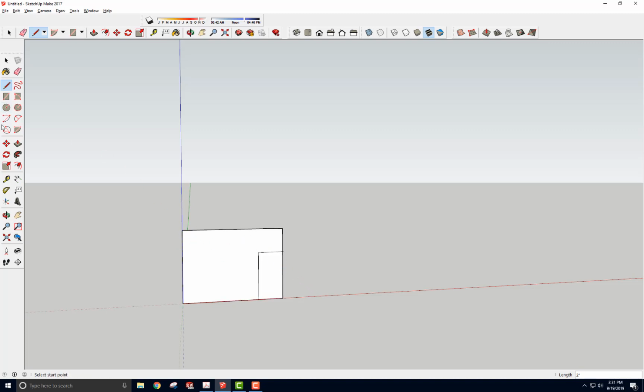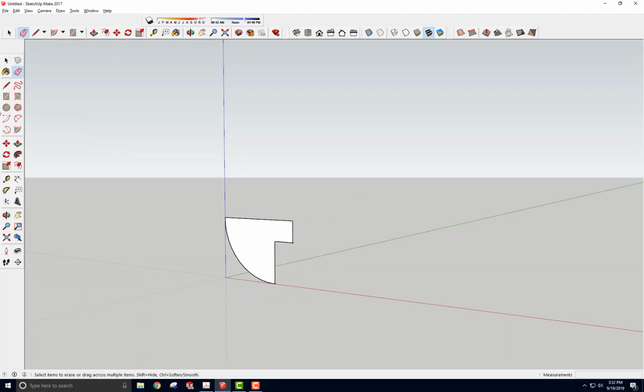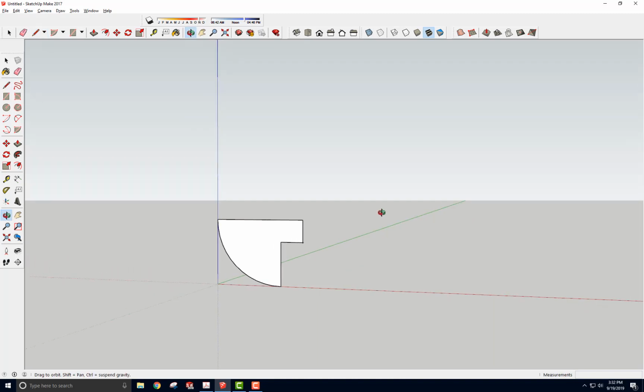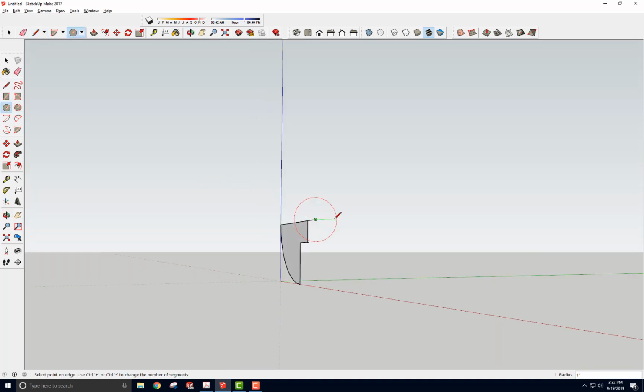And then I'm going to create, using the Pie tool. The Pie tool, remember, has 3 points: the center, start of the radius, and end of the radius here. I'm going to erase this line here, and these two, and this one. And so I've created the sketch of the quarter of this model. Next, the Follow Me tool has to have a path, and I'll need to have it centered right on this edge here, because it's going to rotate around this center. I'll come across, and then use this tool here and create the path.